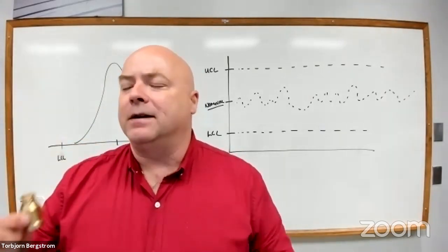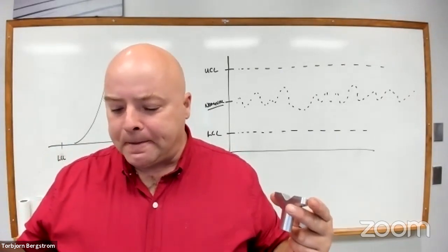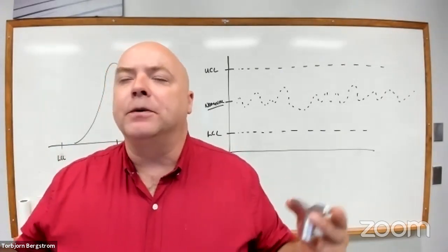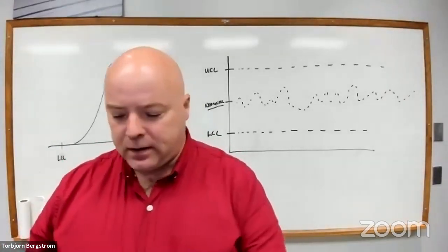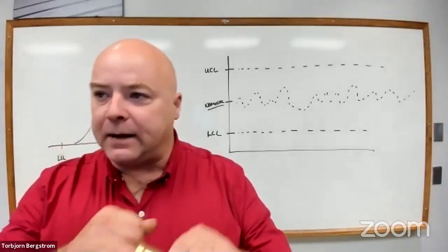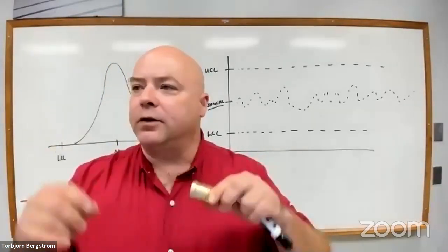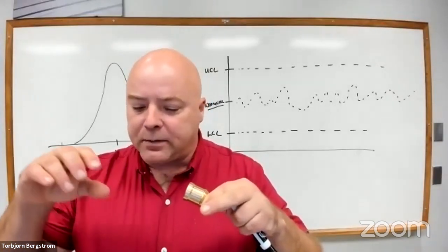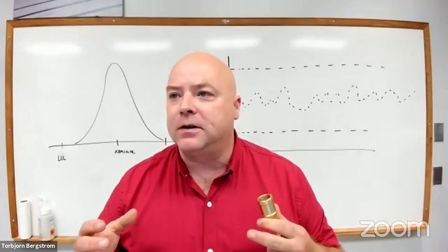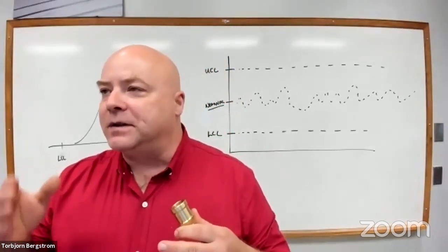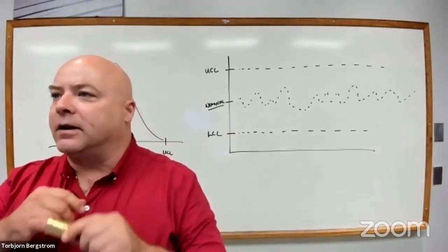So we care about that dimension, but having it vary by up to several thousandths of an inch won't affect the ability of the engine to run. But the inside diameter here, where the piston slides in and out, if we don't control the difference in diameter between the piston and the cylinder to within about 8/10 thousandths of an inch, so 0.0008, then the engine won't run. So that's a critical dimension.